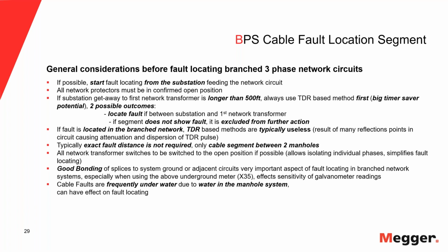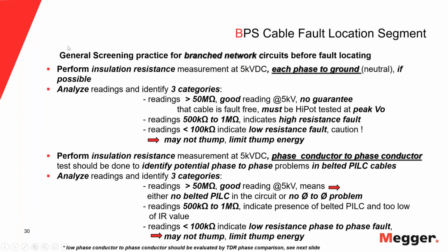Every piece of equipment has limitations, and it's designed for certain things to do. Okay, so what is another screening test now? After we go through some of the considerations, what is a screening test we can do? Again, we can do an insulation resistance test just to get a feel for the insulation resistance, because when we have a fault, typically we expect to get a low reading, or a lower reading than a good cable has. But the fact is, if we know how low it is, it will tell us.